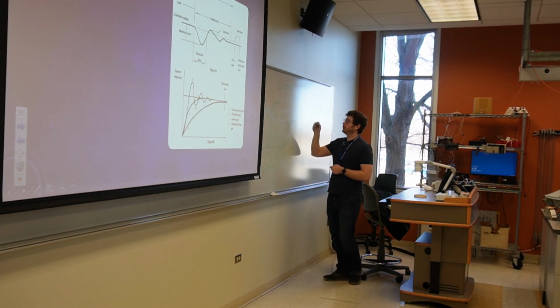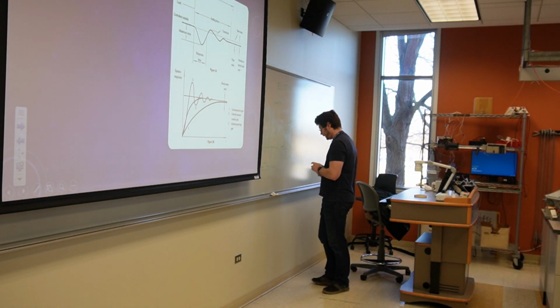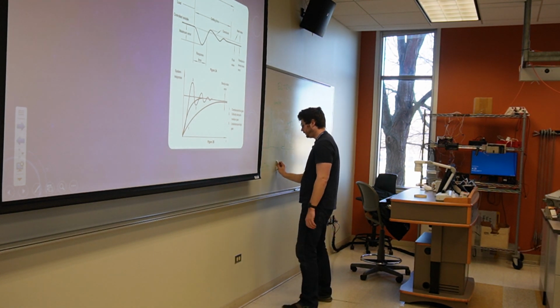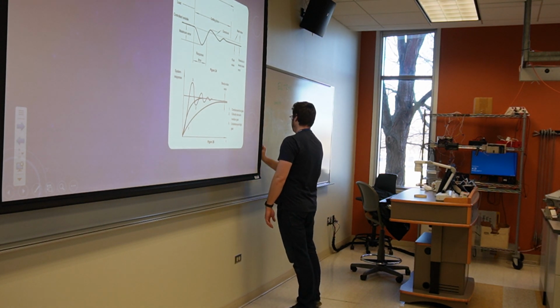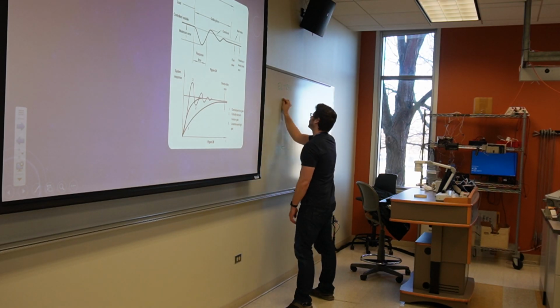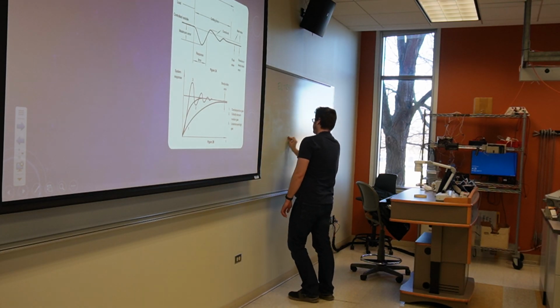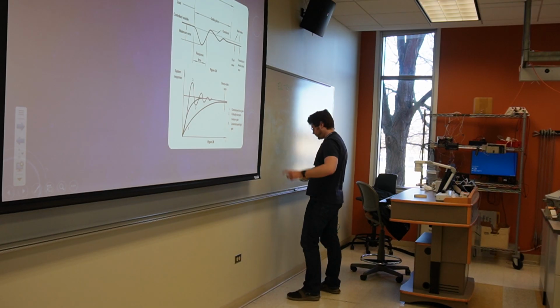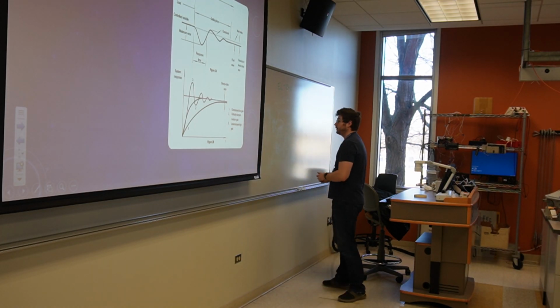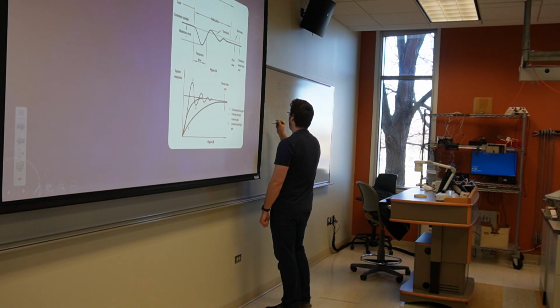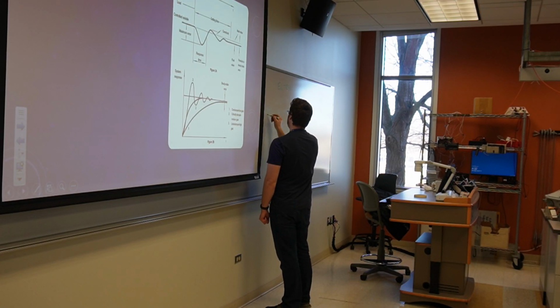Okay. Another thing that you guys will very often encounter, at least in DC electronics, is an RC delay circuit. You saw that T-on circuit, that timer block; we can make that with passive electronics. If we have a voltage here, plus rail, and this is attached to a capacitor, and that capacitor leaks a little bit, there's a resistor on it.